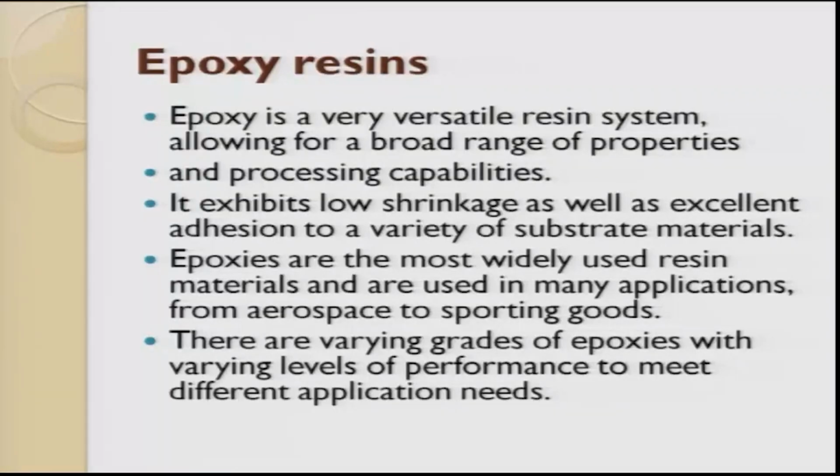Low shrinkage is very important because in a liquid form, when you try to use a resin and when the resin gets cured, that means to say when it is completely liquid is converted into solid, if the shrinkage is very less, then the shape whatever you want, you can easily get it done. If there is a shrinkage, then this can be happening three-dimensionally and it is a little difficult to control the output. But as far as epoxy, since the shrinkage is very low, it gives excellent adhesion with various substrates and it gives very high strength. Epoxy are most widely used in resin matrix and is used in many applications from aerospace